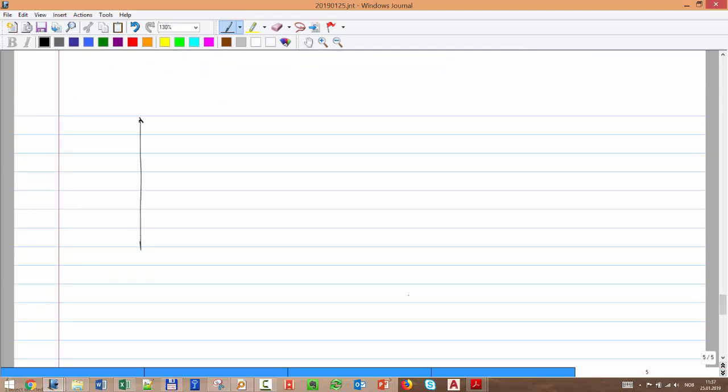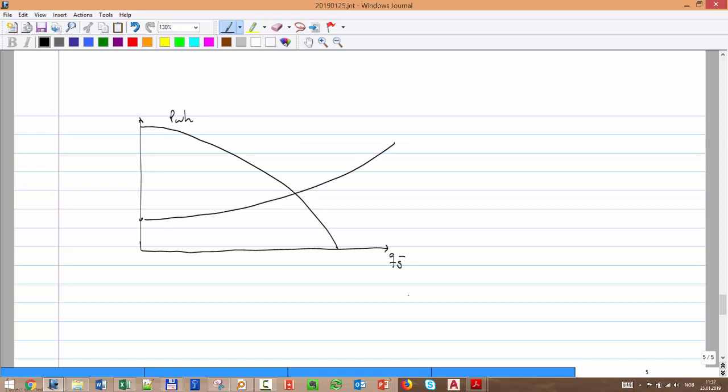So you have the two equations, actually where you had this curve, which was wellhead pressure, and this curve, which was PDC, right? And now I want to add to this curve. I want to make one that will be PDC, that will be PWH, that will be pipeline plus choke. That means if I look at the system, it will be something like this. P separator,